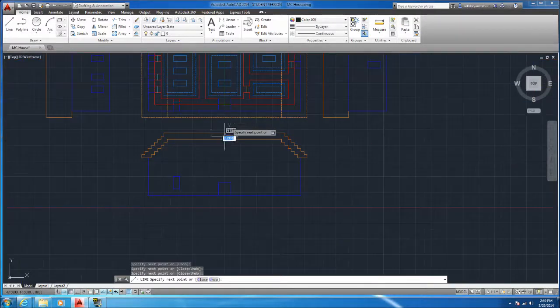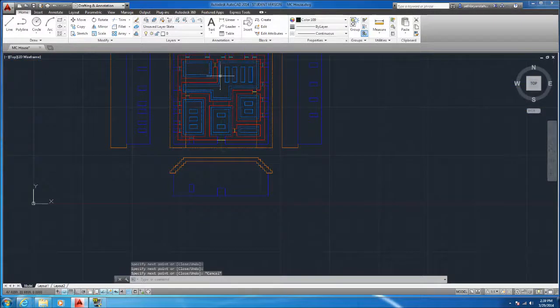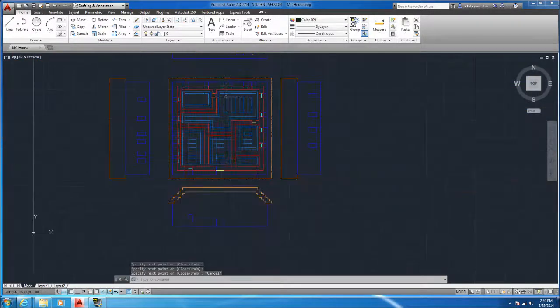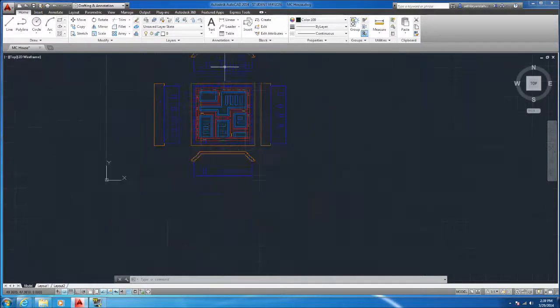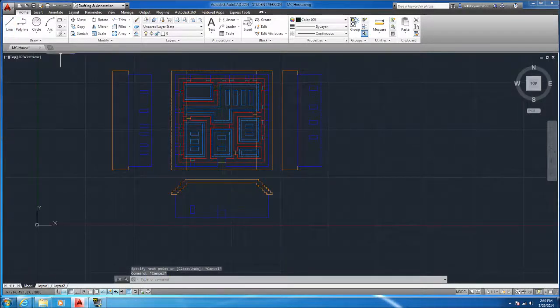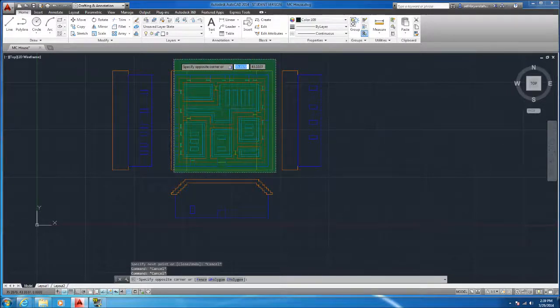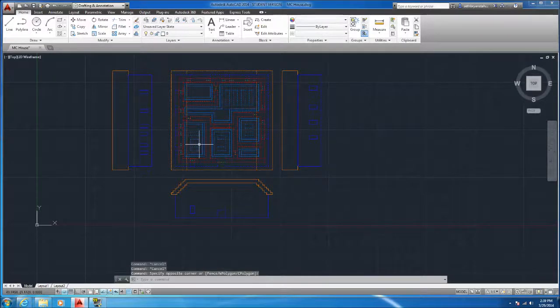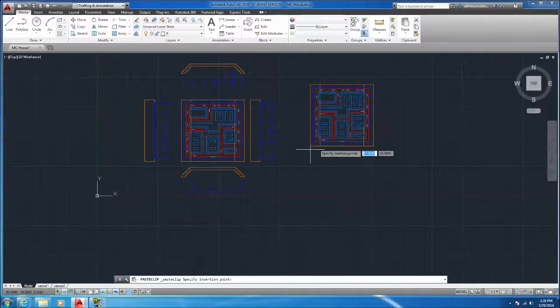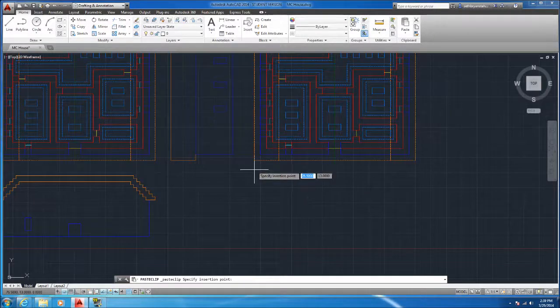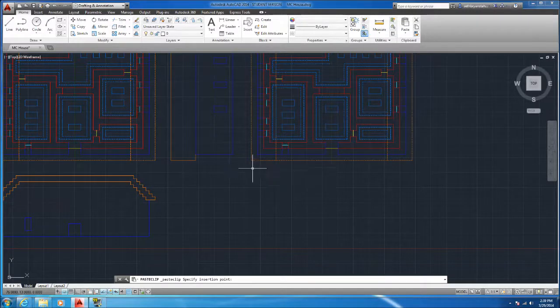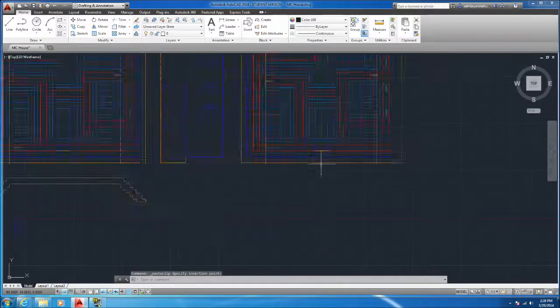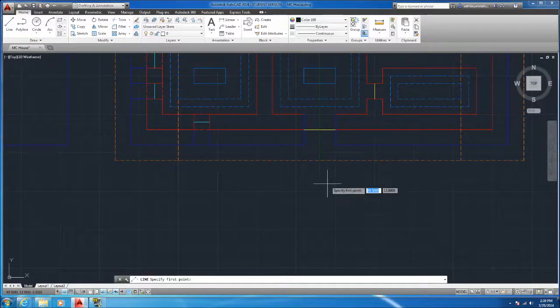Alright. And now, as you can tell, I put those arrows there. It's really important to put the arrows so you can show which way you're looking when you do your section cut. And now the easiest way to do this is to highlight all this. You're going to press Control C, then Control V. Make sure you line it up again. And there you go. I missed some of the lines, so I'm just going to redraw those real fast.